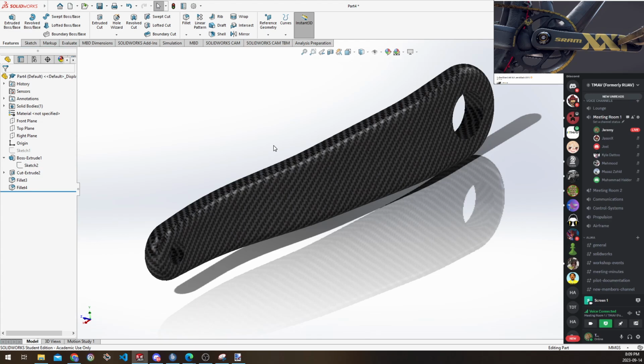A lot of it depends on your specific application. If you're doing custom parts and you're designing everything from scratch that's going to fit together, you have a little bit of freedom over exactly what parts are going to be what sizes and how you're going to interlock them. But if you're designing with off-the-shelf parts, you want to make sure that whatever parts you're getting fit together before you even put them into your CAD, right? So you don't want to buy a part that takes an M4 screw or an M3 screw and then have a 1/8 inch screw instead in your CAD, right?